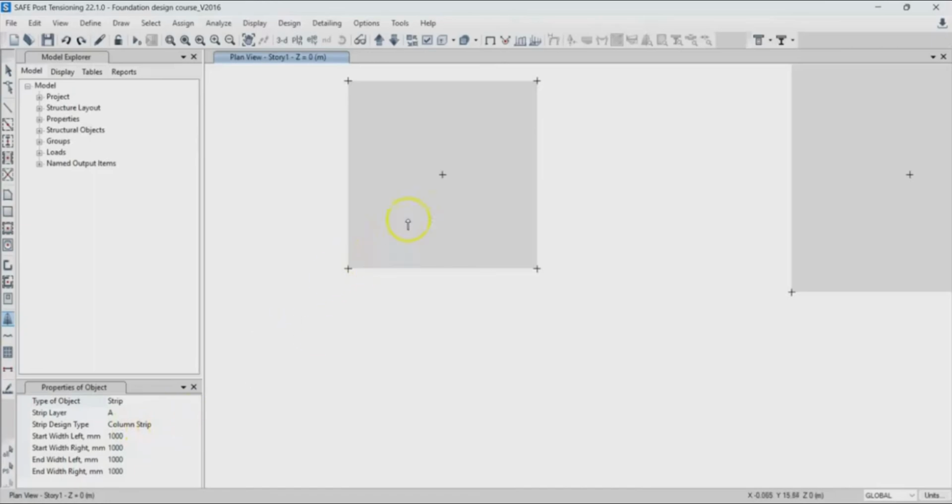Now the middle strip is the part that is far away from the column strip. So let's say this region. This part is far away from the column, so it is going to have very little stresses. And because it has very little stresses, the reinforcement demand is going to be low. So because of that, for this footing design, we tend to ignore the middle strip.